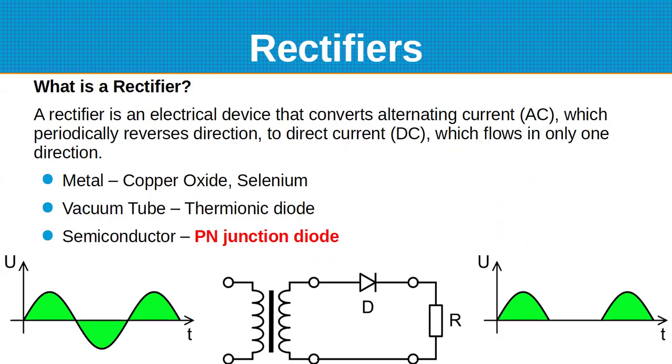If we add, I'll complicate it a little bit, if we added a second diode on this leg and a center tap here, we'd have a full wave rectifier, and we'd pass both halves, the positive and the negative, and they look like positive pulses. So instead of 60 cycle ripple, we'd have 120 cycle ripple. So it's easier to filter.